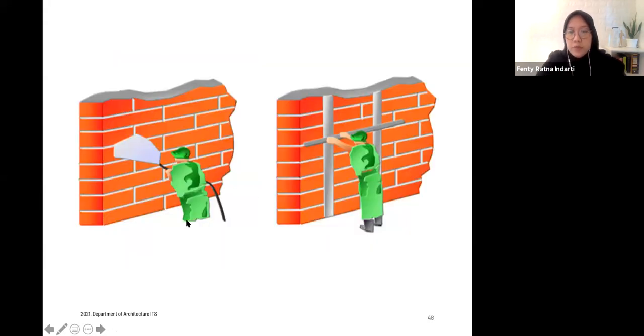And then this is what it looks like, and how to actually create those plasters. Before applying the plaster, you need to make it wet, specifically if you are using clay brick, because when the clay brick is dry, it is really hard to attach the materials, specifically the adhesive materials such as plaster. So to make it quickly, you have to spray it with water like this.